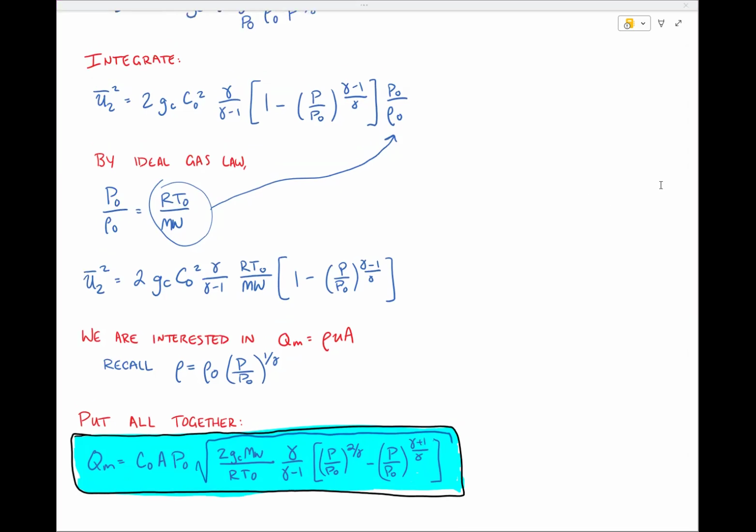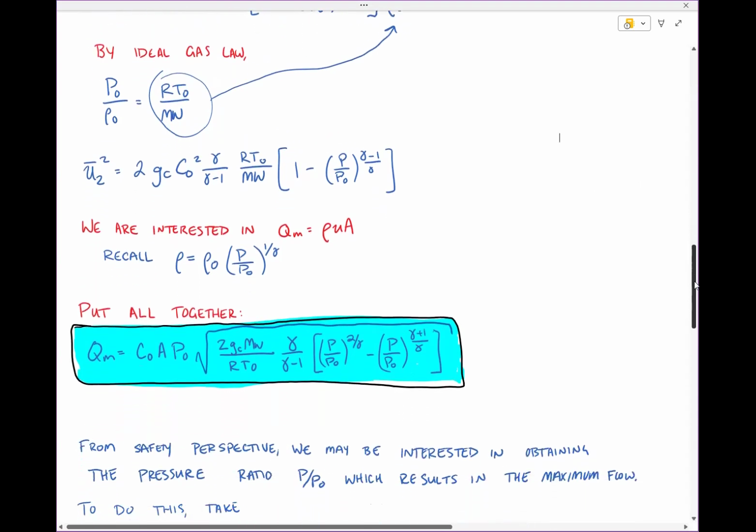One more kind of interesting part is that a gas actually cannot flow faster than the speed of sound. And this is a very common situation. So if you recall back in the T2 video, there was a bystander who said they heard a noise that sounded like a jet engine. And if you've ever boiled tea at home, like in a tea kettle, you hear the whistle. That is vapor moving at the speed of sound.